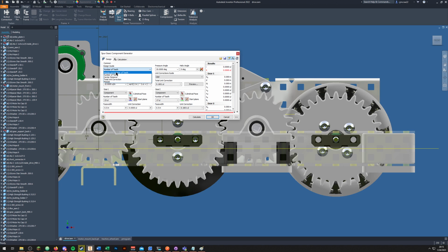How this option differs from this one is that Inventor might not be able to calculate the perfect solution to get this exact ratio with the DP that we preset. Using this option, if it's able to calculate the module and the number of teeth, it'll get much closer to the desired gear ratio. Right now, to use this ratio, we'll get a 23 to 17 ratio.